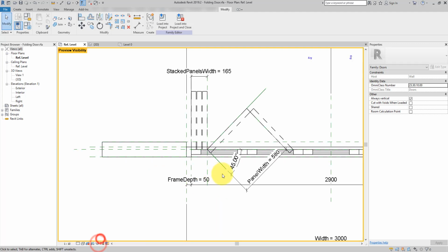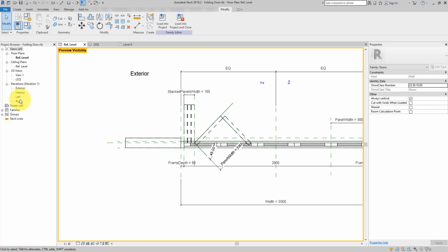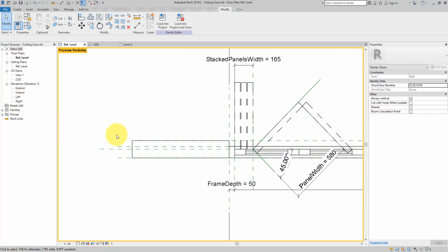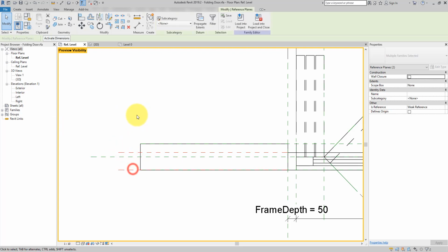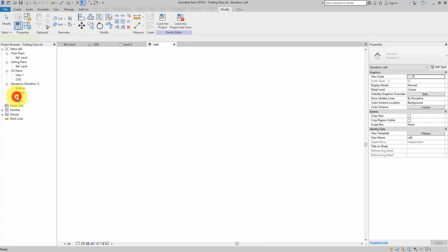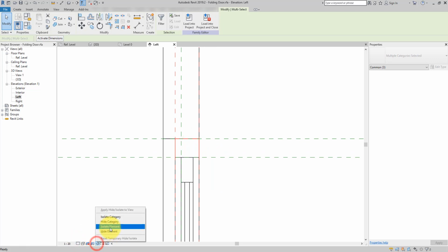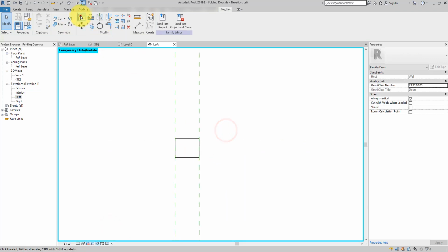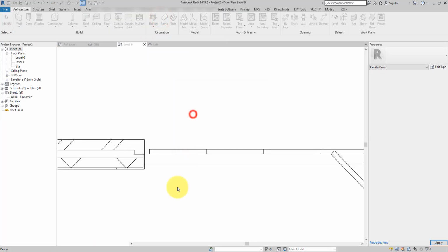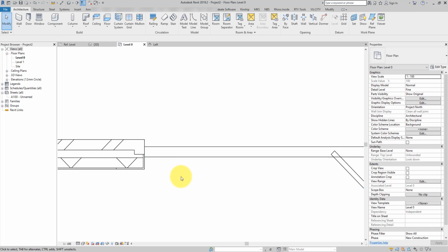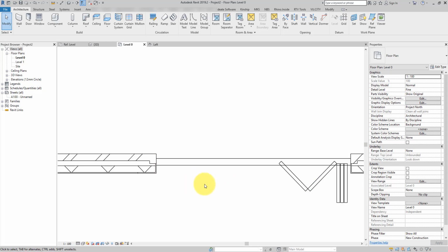Don't forget, we also have the frame on top, so we need now also the side elevation. Before going there, let me select those 2 planes, and then switch to the left view. They are still selected. I can now also control click to get the top frame there, and then isolate the selection. Next thing to do, same old command, align once and then twice. Alright, let's bring this back now to the project. And very nicely, it has aligned with the door panel.